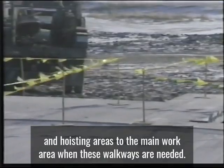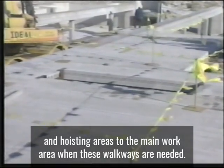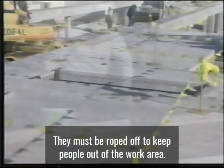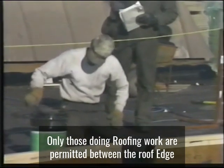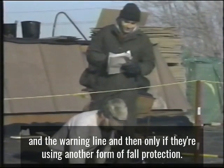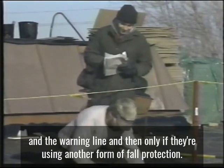A walkway formed by two warning lines is required to connect materials handling, storage, and hoisting areas to the main work area. When these walkways aren't needed, they must be roped off to keep people out of the work area. Only those doing roofing work are permitted between the roof edge and the warning line, and then only if they're using another form of fall protection.